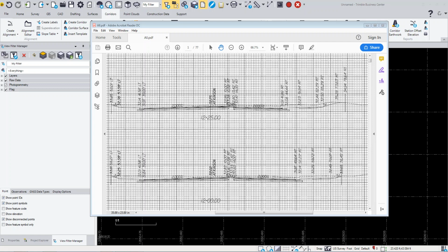In the Surface Modeling Edition, you have the ability to also create stored cross-sections. A stored cross-section could come from a PDF plan set like I have here, or it could be imported from maybe a LandXML file. But in this case, we're starting with basically an alignment, and we want to create this road, and the only data that we have is this cross-section data. We don't have the CAD information or anything else. Maybe from this plan set we entered in the alignment and vertical.